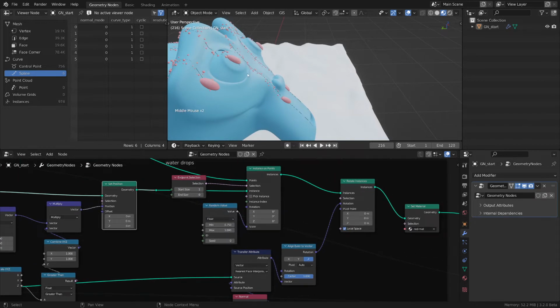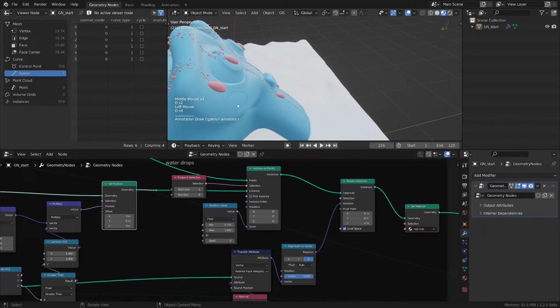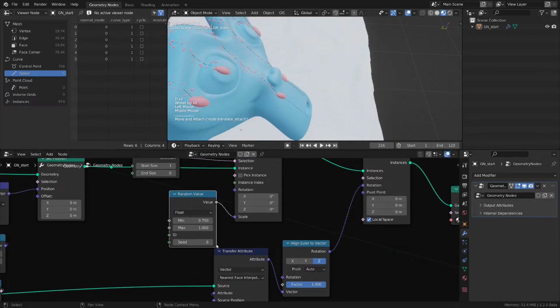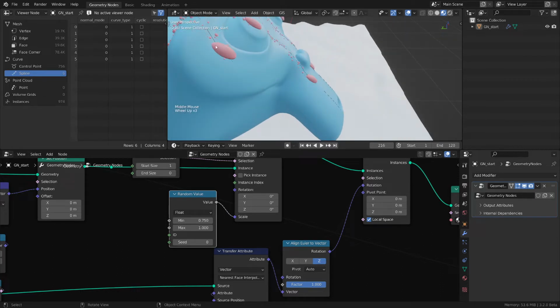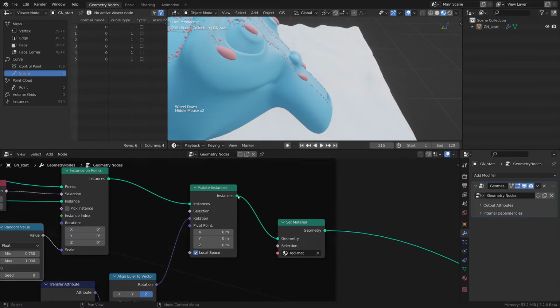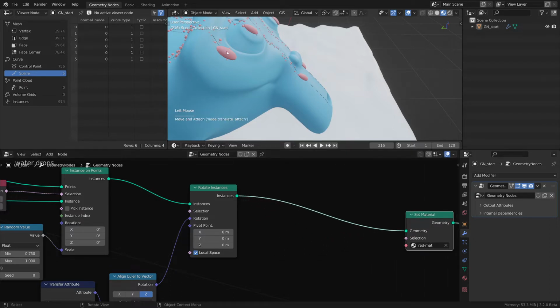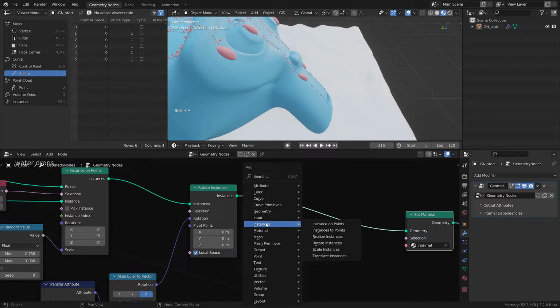We could play with any object with the rotation, as you saw. We can play with the translation, or you can play with the scale and all that good stuff. And we did that playing with the scale here to give them different scales, as you can see. But we are basically altering just the container that has this geometry. If we want to modify this geometry individually, we have to turn these instances, meaning 6 duplicates in this case of the same geometry, into a real geometry.